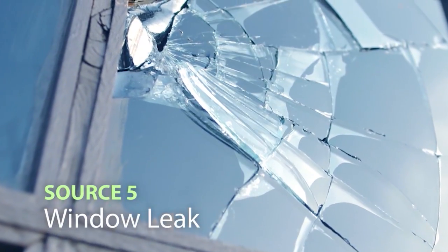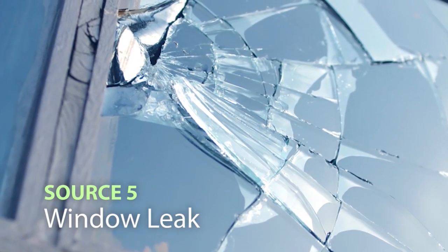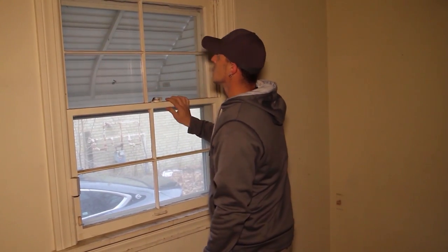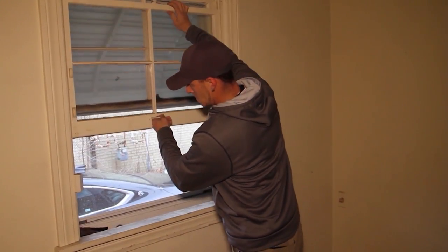Source 5 is a window leak. Examine the seals on the windows from the outside to ensure there are no gaps. Check the interior for water damage, wood, or gaps between the window and the wall. Make sure the windows open and close correctly and that the glass is intact.